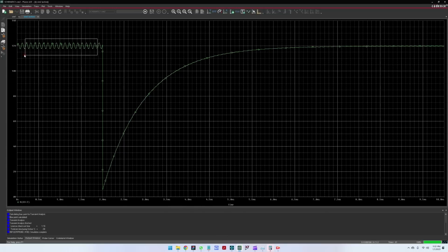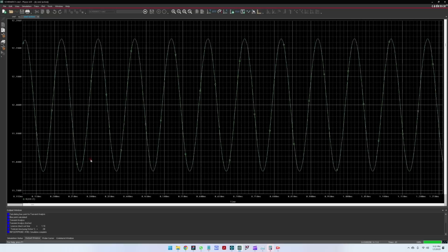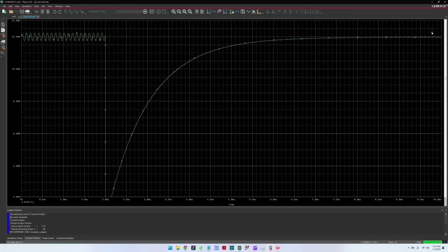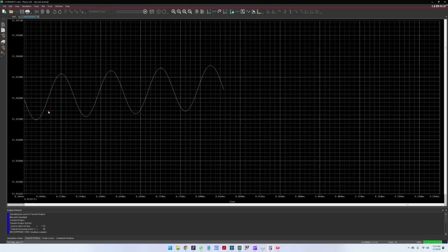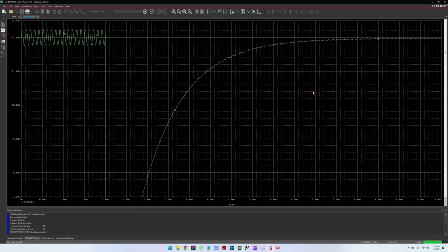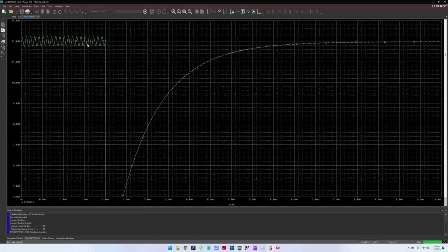So we can see here, this is the bad ripple. We have here a 250 millivolt ripple, and you can see here after the capacitor is added, you have like, I don't know, this is 20 millivolt ripple here. So this is many times higher than the output ripple.